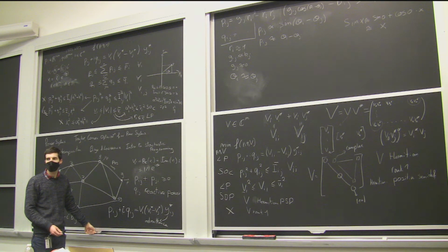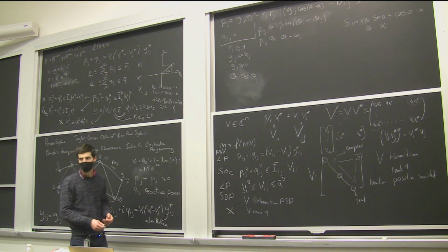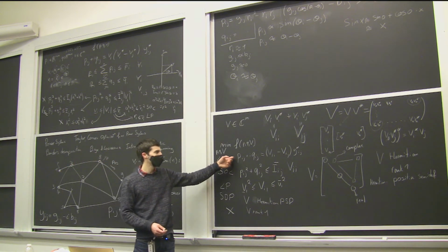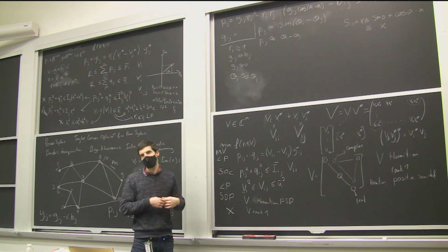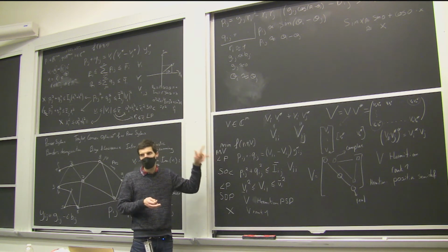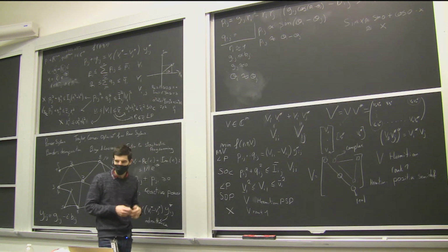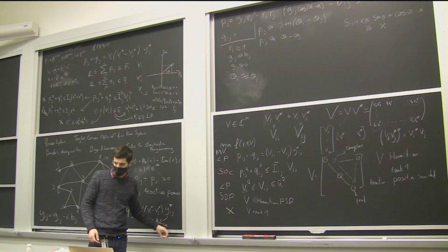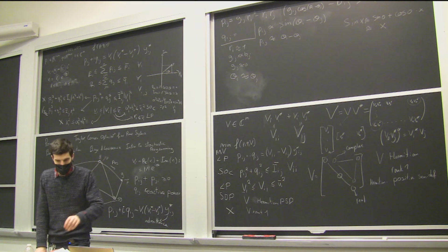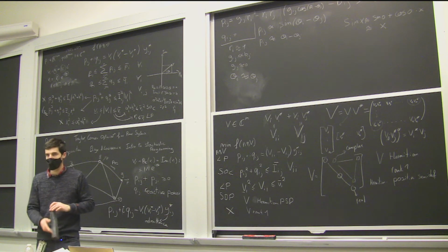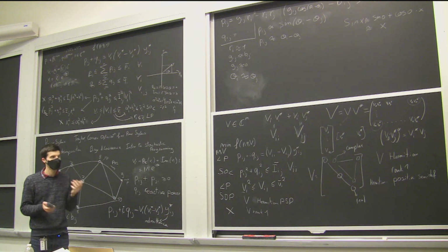Yes. So the Pij plus i Qij, right? When you actually optimize, you're going to optimize for two real number constraints, right? Yes, basically the scalar components. It's like a two by one vector, essentially. Exactly. So this is one inequality in the complex number, and in fact it will be two equalities for your solver, which will be in the real numbers. So we always do that. There's no way to directly optimize with complex. We always just convert to these vectors.